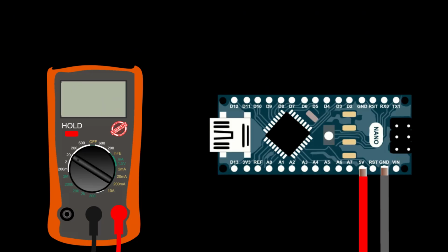To measure voltage with a digital multimeter as shown, you must first select the correct mode of the meter. Some meters have an auto-ranging feature, and other meters must have the range manually set with a switch. If the range is set too low, say to a 10-volt scale, and the meter is connected to 200 volts, the meter will most likely be damaged.